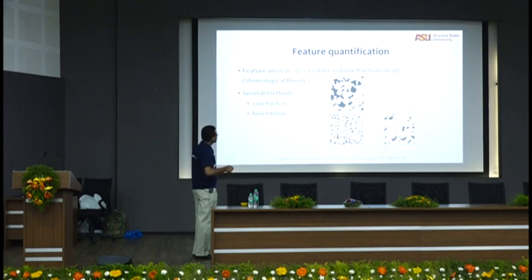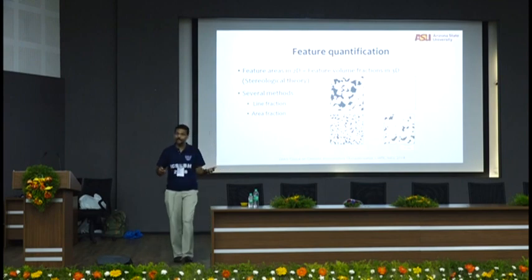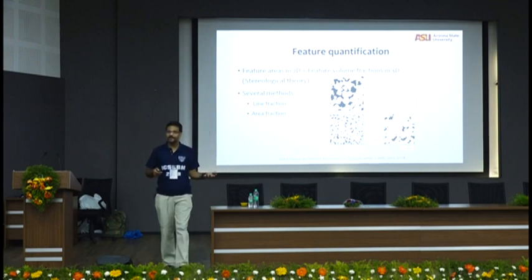You see here? It draws a lot of lines this way, and then wherever there is no black area, it cuts off the line. So here the lines are only where there are black areas. And then what it does is, it adds up the length of all these lines that you see here, divided by the total length of all these lines. You see, you get a good estimate of what the porosity is, right?